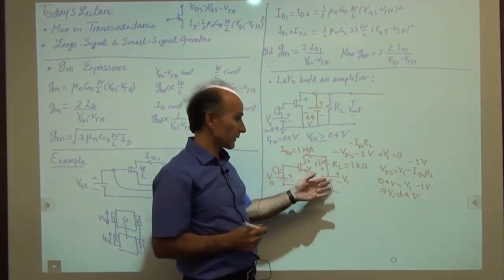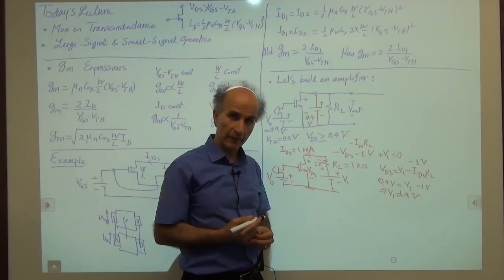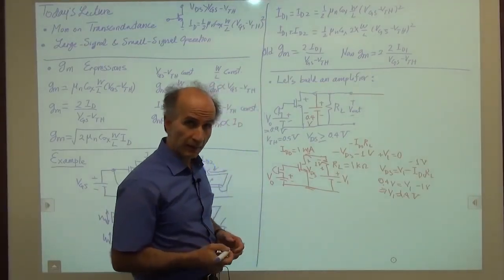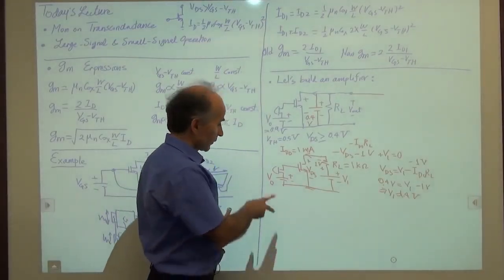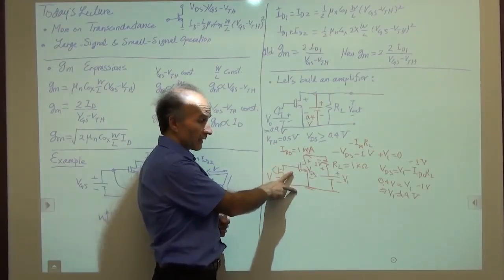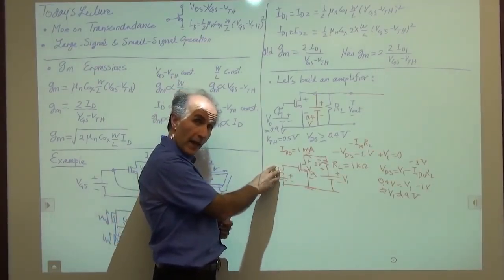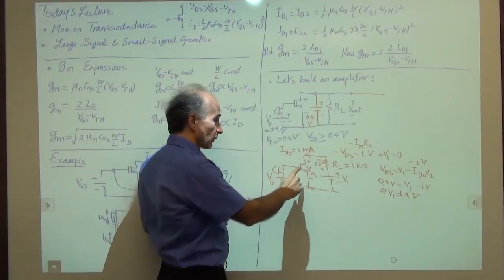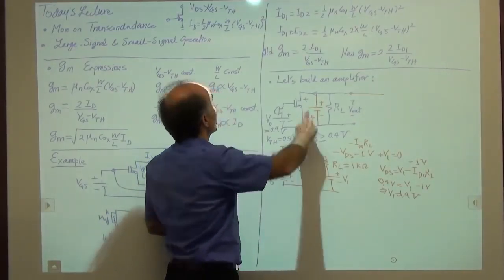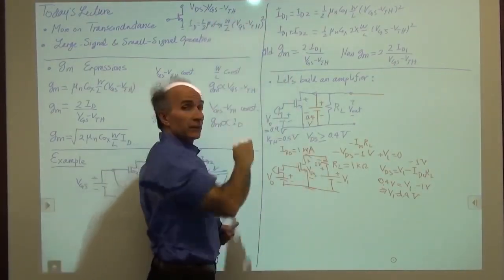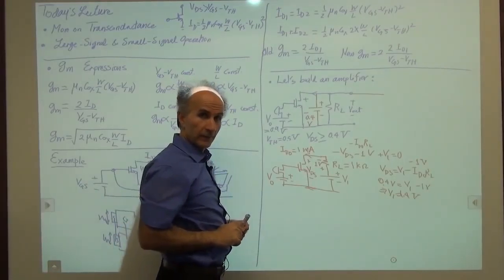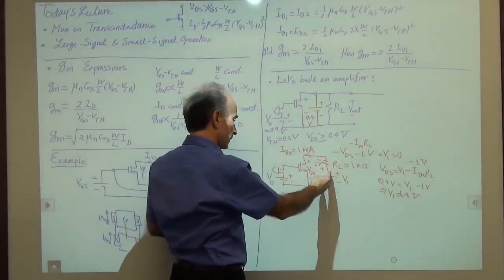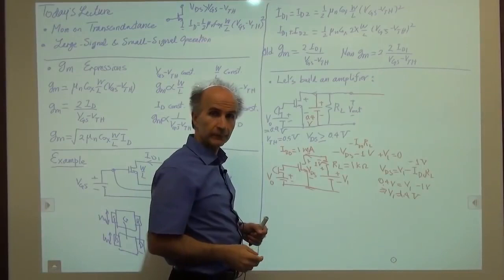All right, so this allows us to provide this proper biasing. So proper biasing of MOSFET requires some sort of voltage between gate and source when there's no signal, and some sort of voltage between drain and source, so that this condition is satisfied, right, for saturation. That means that we need a battery here and we need a battery here.